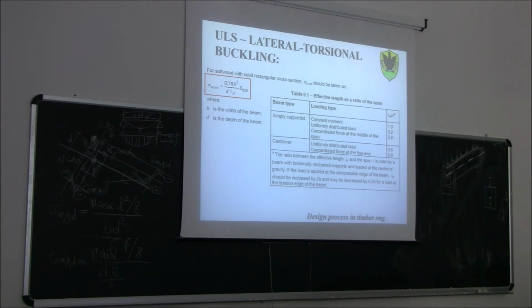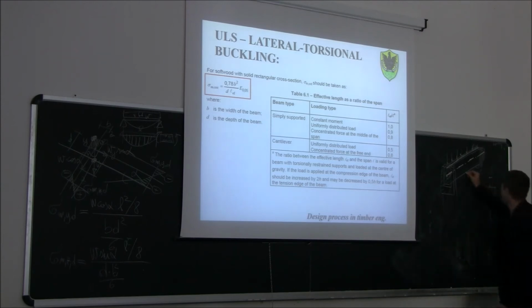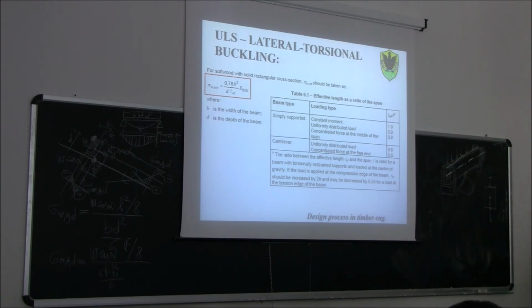So we have an additional torque moment given by the load times the distance e from the center of gravity. If instead the load was applied on the bottom of the beam, for example, you hang here like a big lamp on the beam, is this positive or negative?